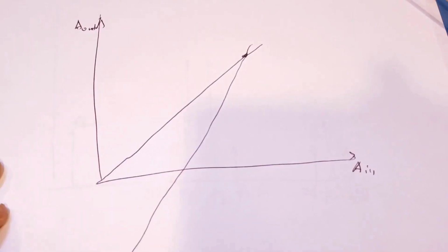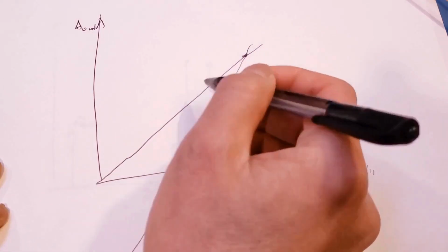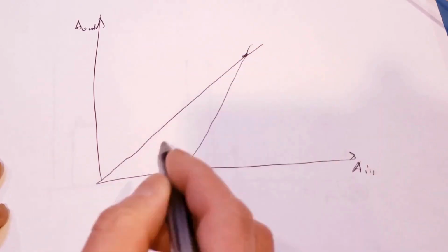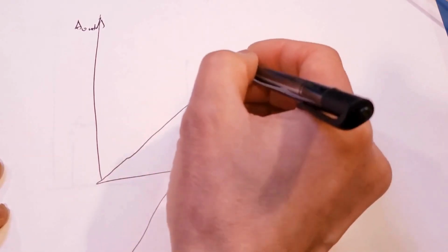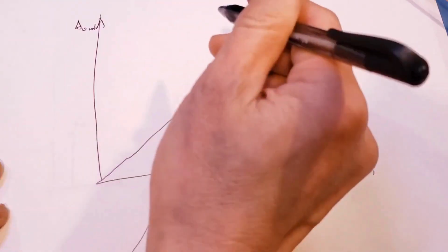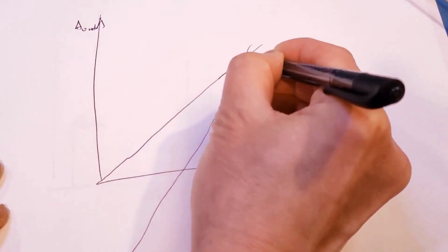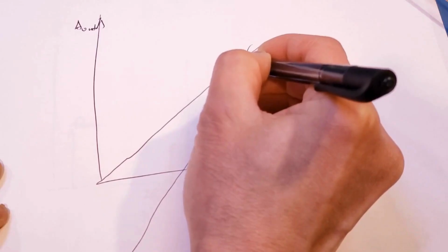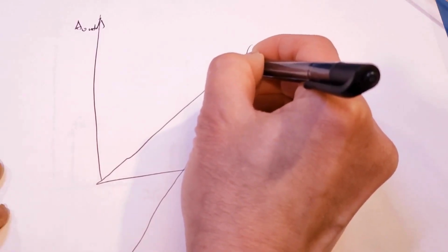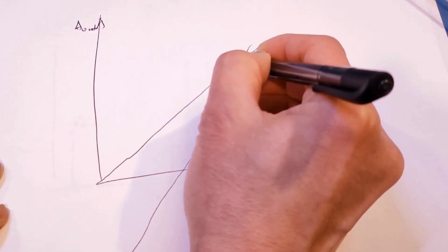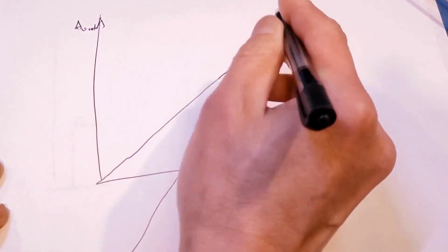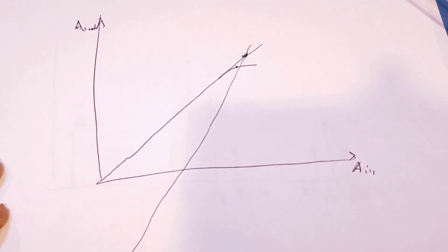And you will often hear the term 1 dB compression point, and that's where the transfer function is no longer linear and output is compressed by 1 dB compared to the ideal output. So for example, here's our input to output relationship, and that's linear. Of course, at some point, as the input amplitude increases, the output will no longer be able to keep up this linear relationship, and therefore it will saturate. So for example, here, it gradually saturates. And the 1 dB compression is essentially the point where, for example here, the actual output is 1 dB down from the ideal linear output. So that's our 1 dB compression point.